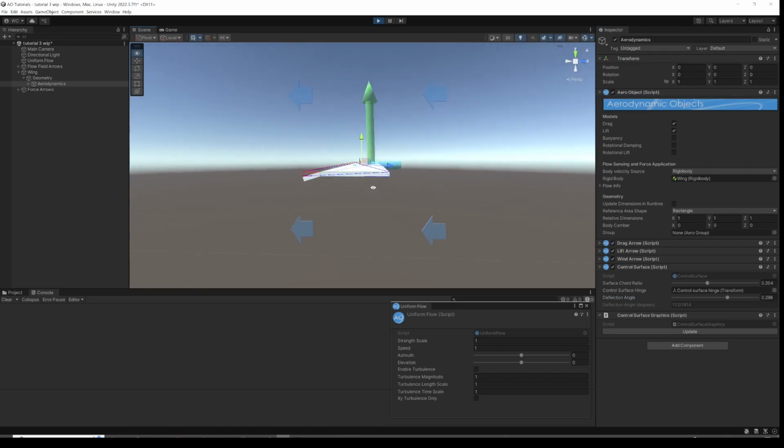The aerodynamic theory of this is reasonably complex, how a control surface works, but the simple way of thinking about it is effectively you're changing the average angle of the surface. So when you deflect something down, if you imagine you joined a line between the trailing edge and the leading edge, it's sort of more at an angle, and that's increasing the effective angle of attack of the surface, and that's producing more lift.